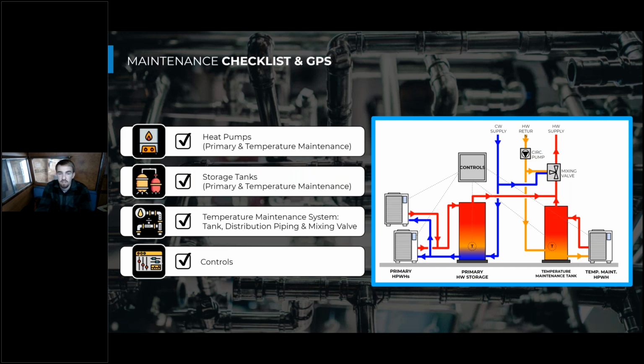There are often different sections of the building that have different distribution loops serving them. So you want to make sure that they're receiving consistent hot water in the amount of time that it was received in the initial installation. Even if equipment builds wear on it, it should not cause longer wait times for hot water in different apartments. That's really important because we want to be really careful about the amount of water we're using.